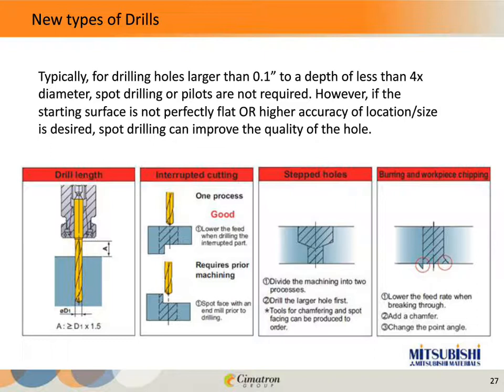The third illustration here shows a step tool. When I see this, I think about a counterbored water line, like in a mold application. And I actually did run a boring mill for quite a few years in my early 20s. I remember that in a hole like this, I would have drilled the water line first and then thrown a big high-speed steel drill in there and just chased that smaller diameter.